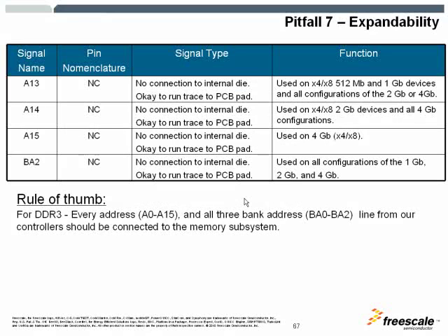If you're building a board and you are considering an option to keep it for a while and expand the memory size, make sure you leave options open for yourself and leave the footprint available so you can expand it by soldering different DRAMs at a later time.